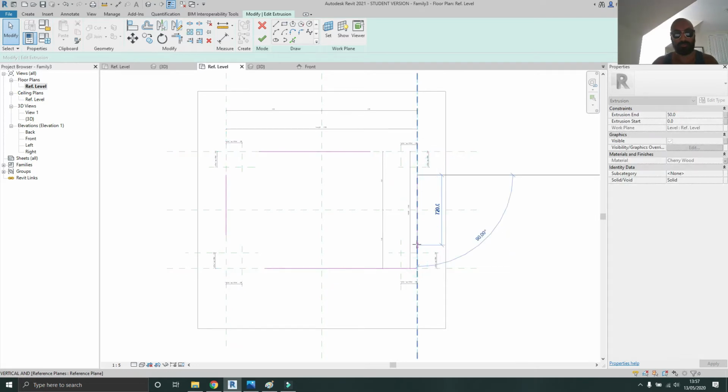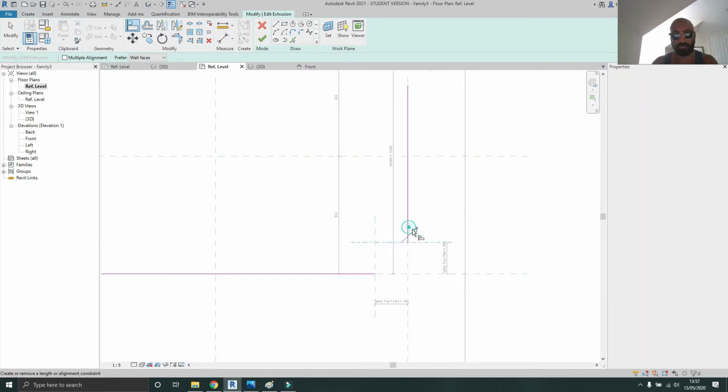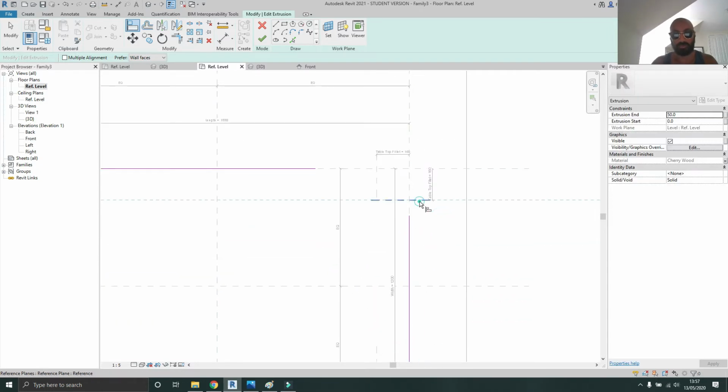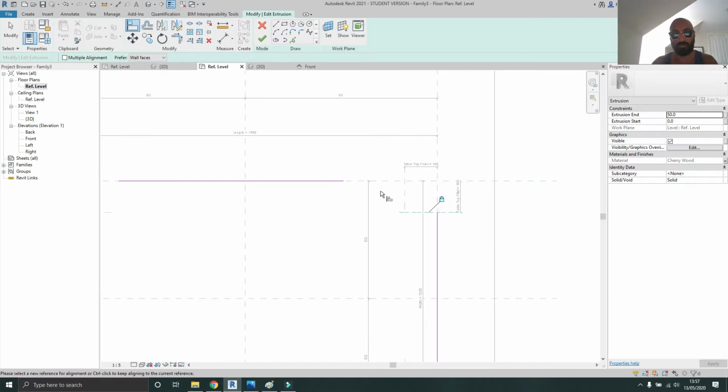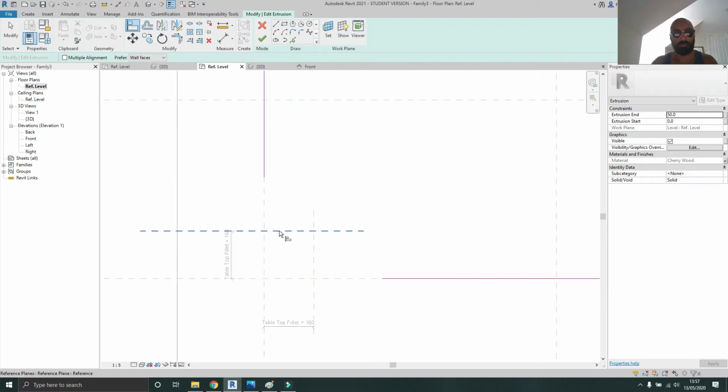And I know it looks like there's an easier way, but the reason I'm doing it is just to make it easier to see things. So I type AL for align, I want to align that to that point. It's the point we want. So we want to make sure we've done the correct point. That's why I'm dragging them back manually, so that I can see the visual confirmation also that they are done. And then that last one.